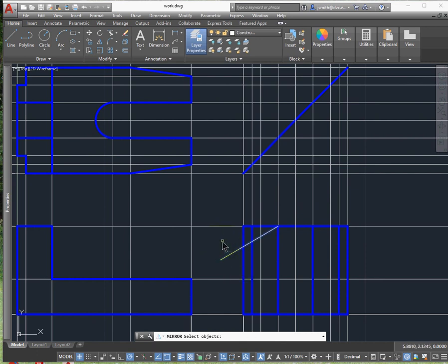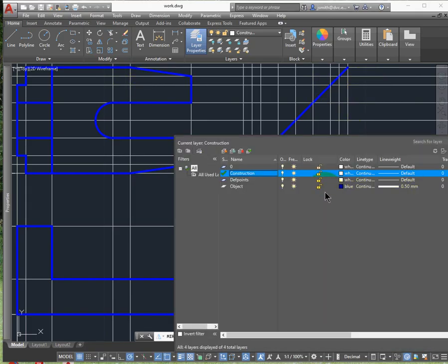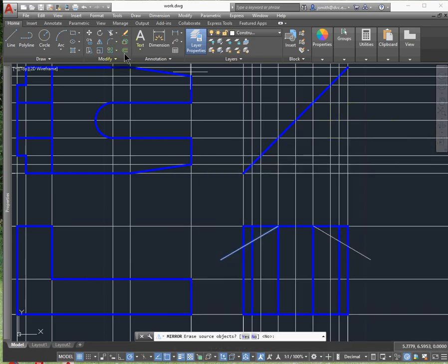And so I'm going to need to make a construction line based on that so I can see where the line goes in my side view. So I went ahead and mirrored that line. And I don't want to delete it, so I can just push enter. All right, so we need some more lines. I'm going to build another construction line, a horizontal one, at the intersection where that line is meeting the outside of the part.